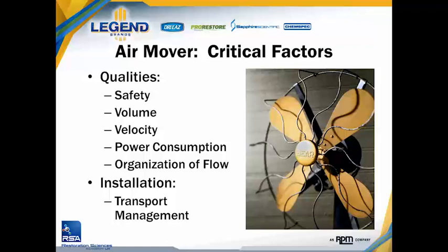Obviously, they need to be able to operate safely in an environment over several days, if not a week or more on end, in order to allow occupancy in the space, or other contractors, or even your own staff in the space while they're operating, especially in a damp environment. They need to generate a substantial amount of air in order to affect a good number of surfaces. That air volume also needs to be moving at a great speed. It's not just the amount of air generated by an air mover that's important, it's the speed of that air that's also important.